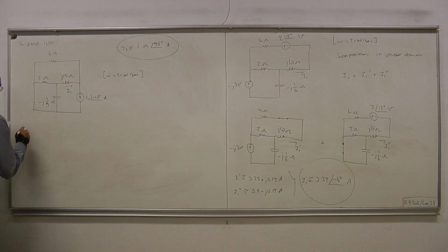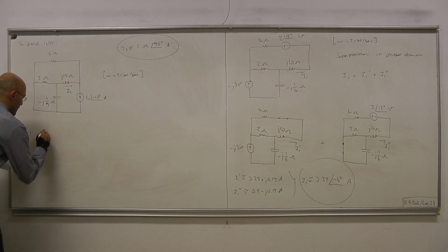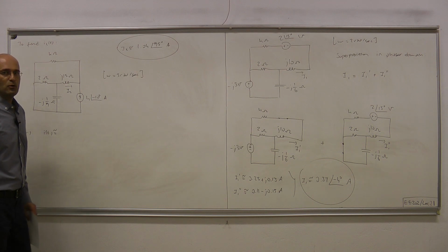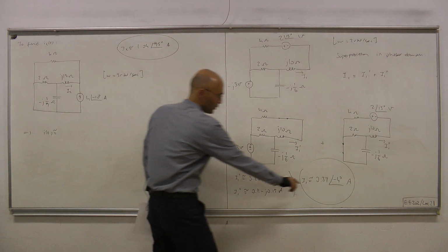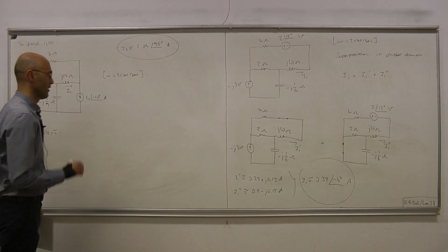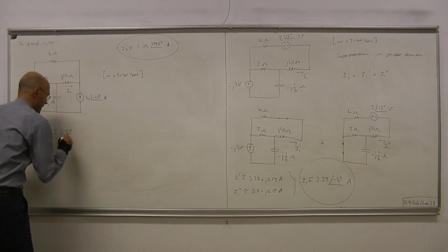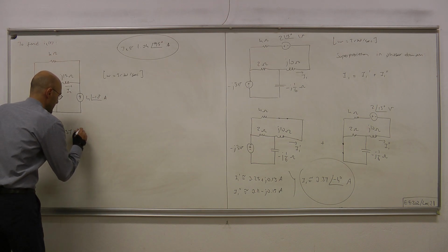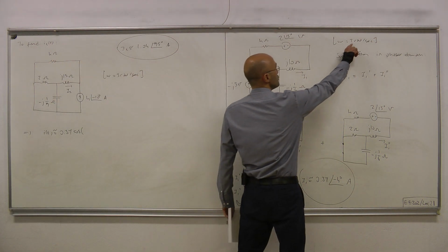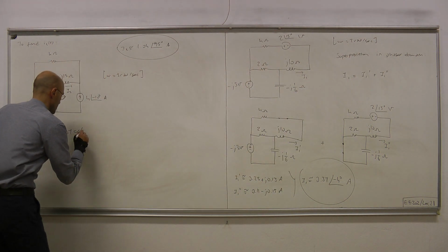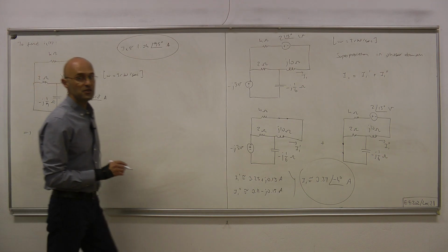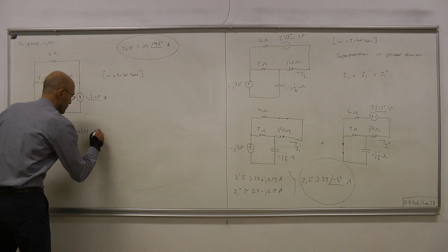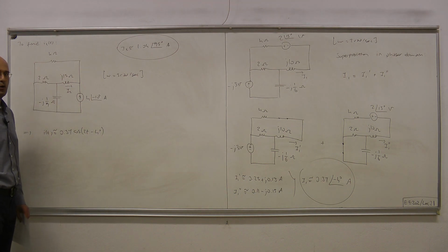Okay, therefore I of t approximately equals I1 of t. What's I1 of t? We look at the phasor of it. So I1 of t will have the amplitude 0.37. It's oscillating at frequency 2 radians per second, 2t, and the phase is approximately minus 4 degrees. Minus 4 degrees, okay? So that's our I1 of t.